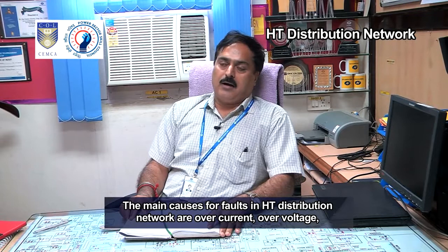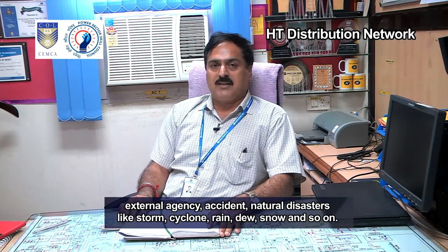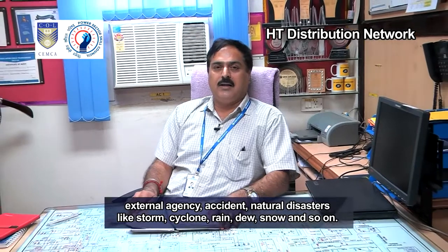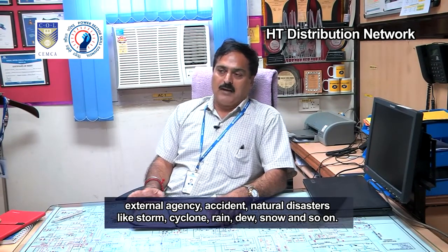Sub-transmission network comprises 66 kV, 33 kV and 11 kV network in a distribution company. The main causes for faults in HT distribution network are overcurrent, overvoltage, external agency, accident, natural disasters like storm, cyclone, rain, dew, snow, and so on.